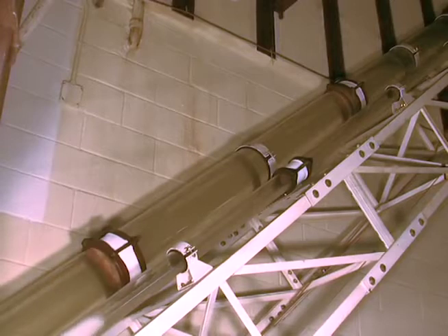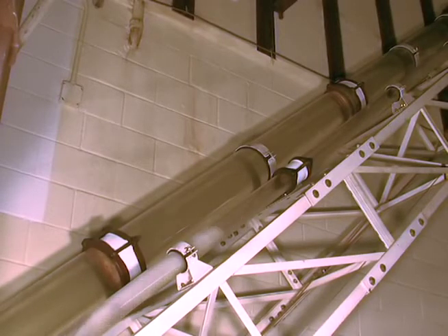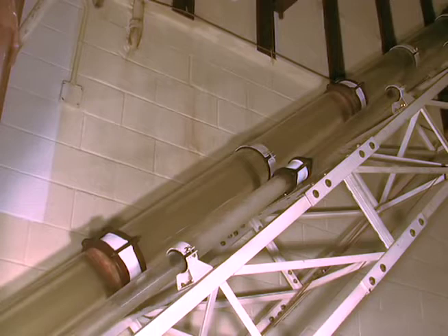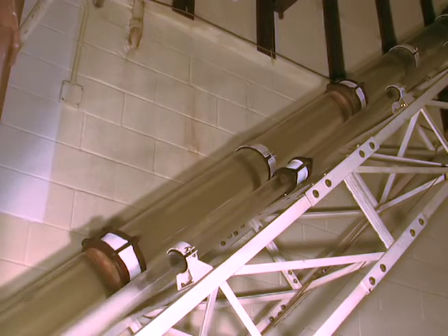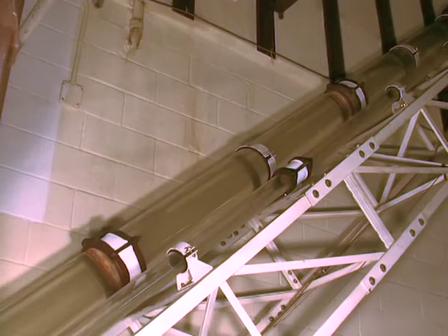The flow tube has now been increased to a 45-degree angle and the gas rate reduced to 30 MCF per day. This produces a bubble flow moving up the upper side of the large tube, and stratified flow coming down the small tube.